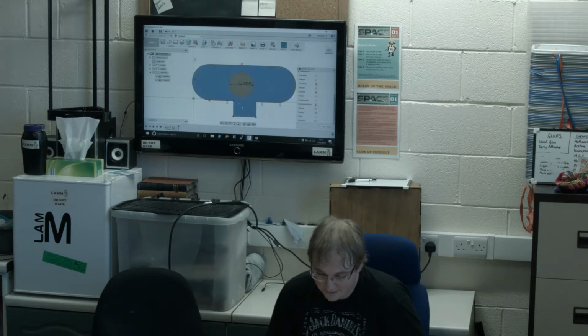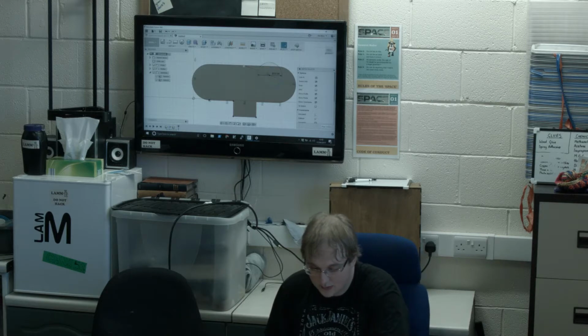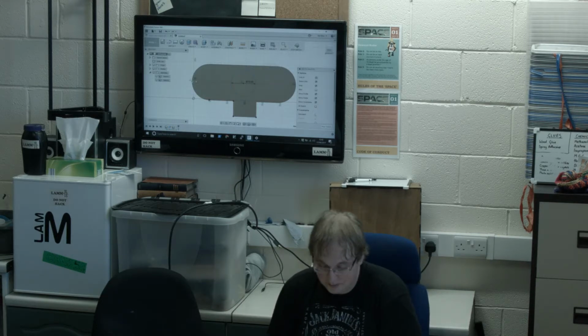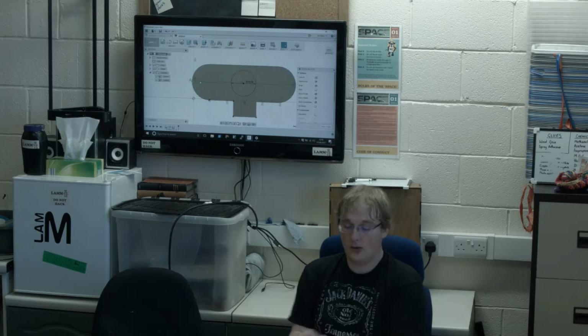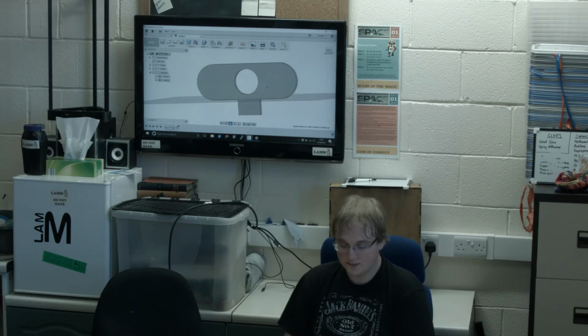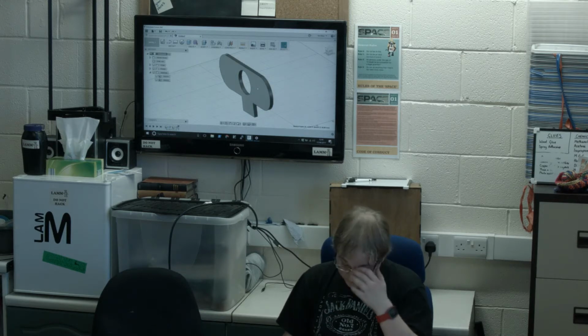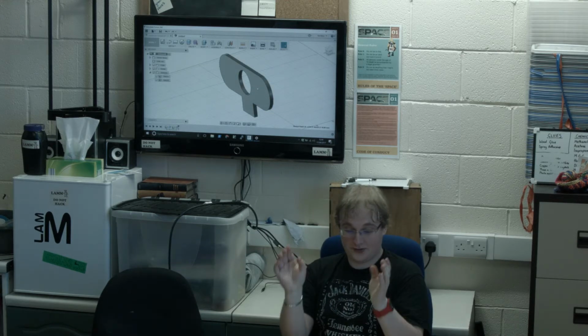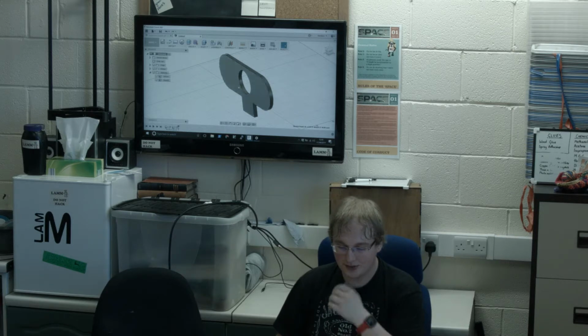Not the vertical, couldn't you? Yeah, so I could actually snap that there and take that constraint off. And then do it across the way, and literally, I'm just dragging lines around here. Yeah. So this is like, oh, I need to do it the other way, and then we're done. We still have a signpost. So there we go. That's a very quick introduction to that side of things on Fusion.